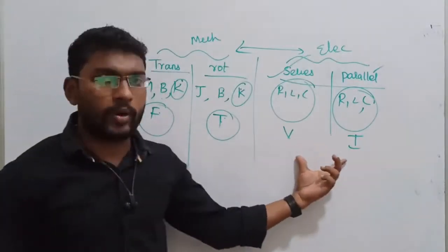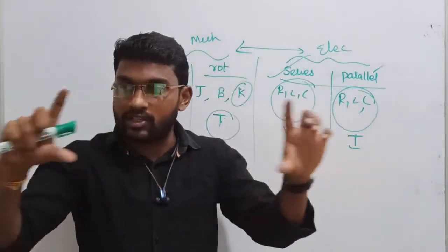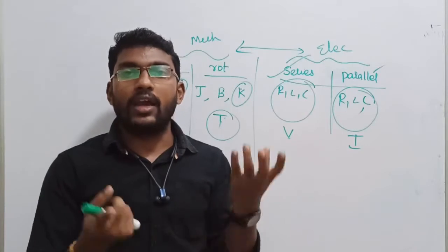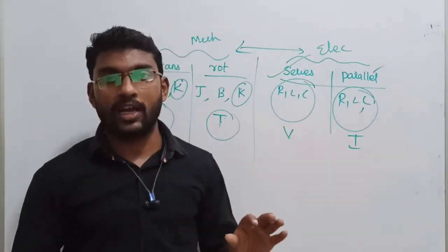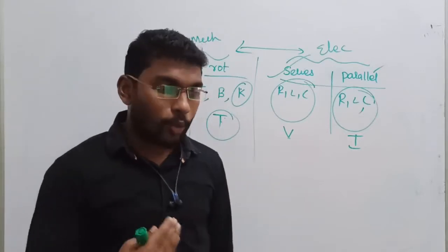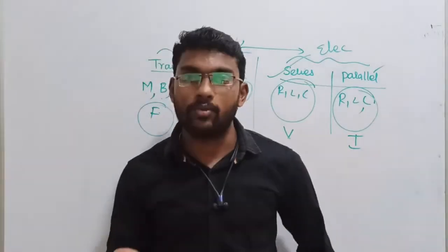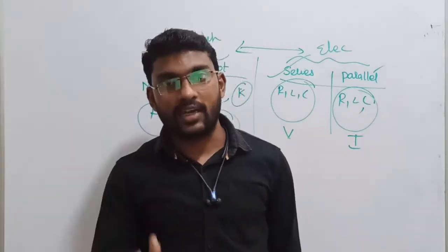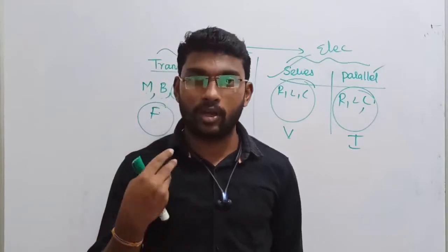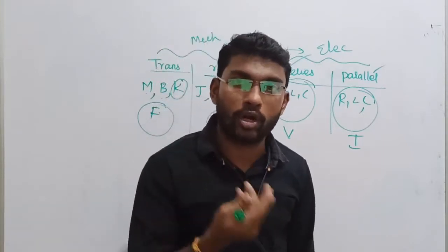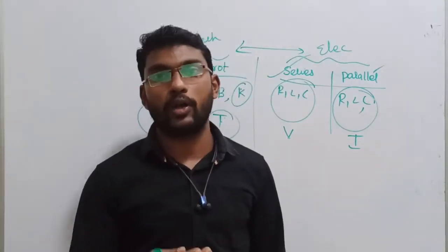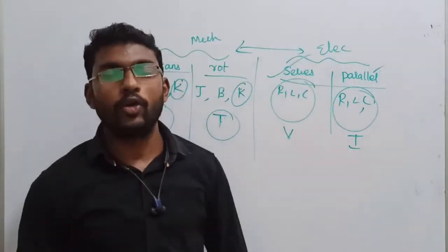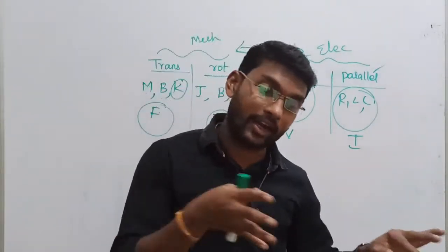And then in the electrical domain, after getting the mathematical equation, the differential equation, we can apply Laplace and identify the corresponding poles. After applying Laplace, we can see the poles and zeros, what the type of the system is, what the order of the system is, where the poles are located, whether the system is marginally stable or unstable, whether it is a second order system, and what the damping ratio and the value of K are. We can put it in a root locus, draw the Bode plot, the polar plot, the Nyquist plot, anything you want. You can play with your system once you enter the electrical domain.